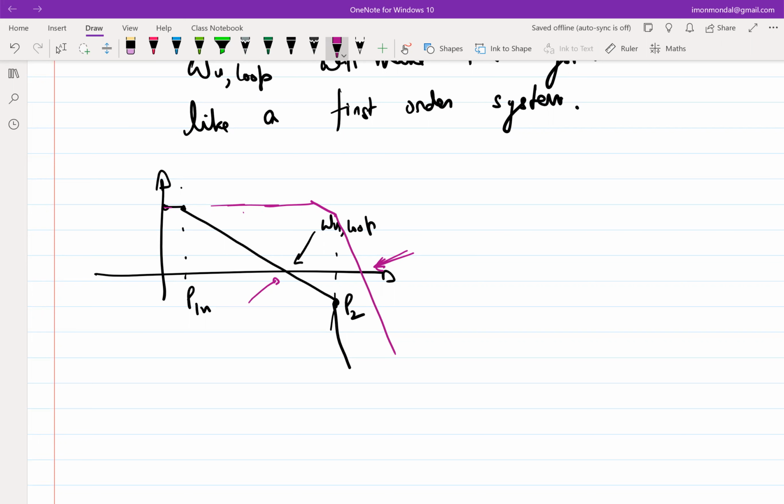So there are many good things about negative feedback. One very bad thing about negative feedback is it tends to make your system slower. Because if you are trying to make very fast systems using negative feedback, which essentially means that all the poles are at very high frequencies, the poles are probably even bunched together. If all the poles are bunched together, then you put in negative feedback, you will have an underdamped response. So in essence, in order to make your system stable, you'll have to separate the poles. I have made all these arguments with a two-pole system,